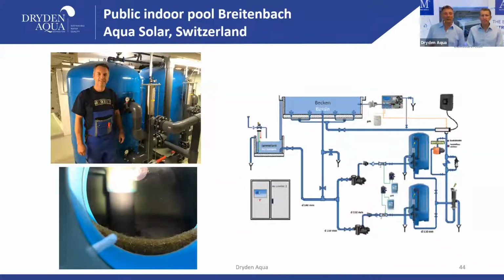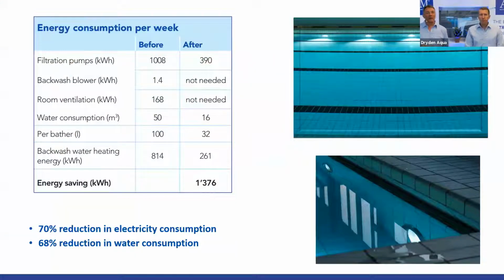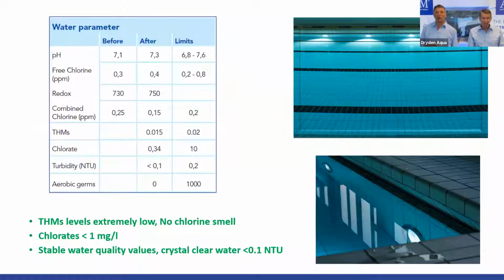We talked already about this. We also did some good energy savings, because they didn't have a frequency controller. They had huge pumps, but no frequency controller. So we installed frequency controllers and flow meters, and this is where we made really good savings in energy, but we don't want to talk about this. I want to talk about the water quality.